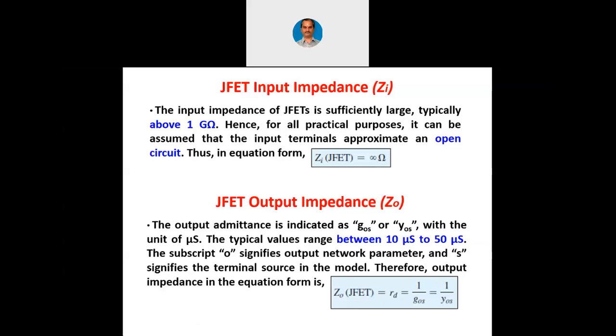That way we have impedance matching there. And I had told you earlier that you will be studying a theorem called maximum power transfer theorem in the course called network analysis, where you will understand that when two impedances are equal, only then highest power will get transferred. When the source impedance and the load impedance are equal, then the highest power gets transferred.